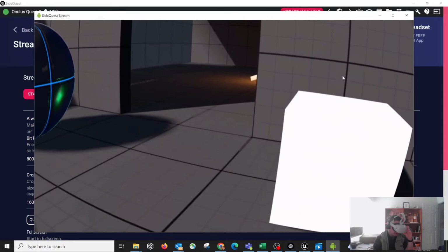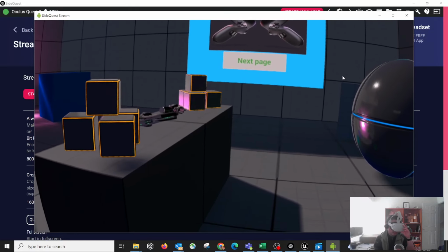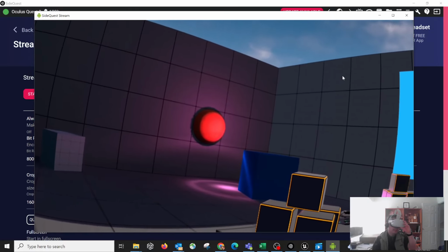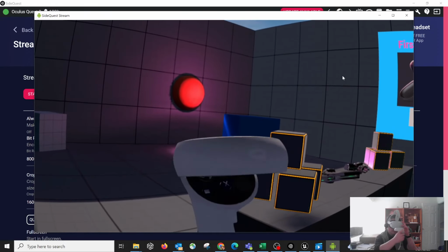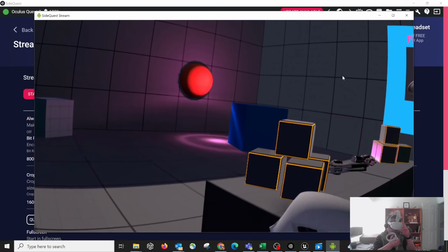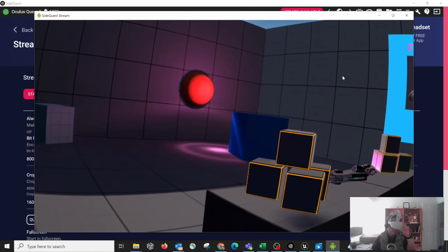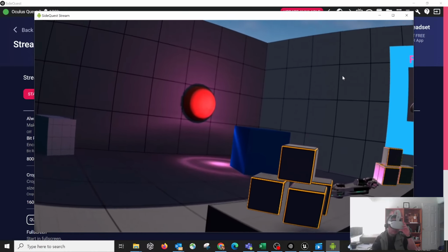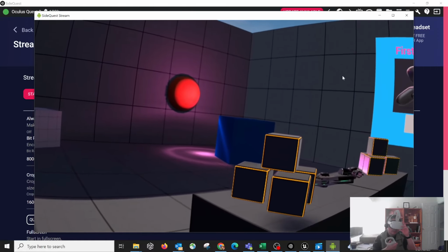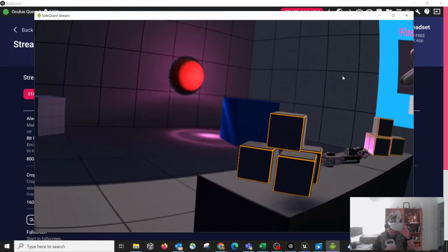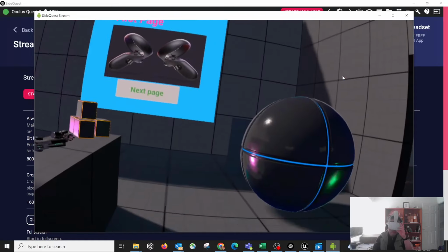So here, I can go ahead and navigate the other side. You do see the IES lighting is actually available because I treat this as a static light, and I use the IES for the light profile. Once you bake the shadows, the light map is actually recognized right there, so it's pretty cool.